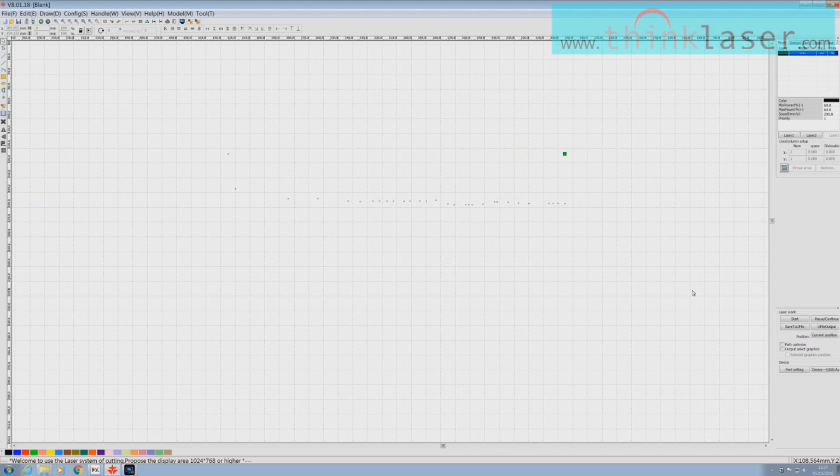with the keyboard. And then what I can do is box them all in like this. I can go up here to my commands, and first of all make sure they're all centered horizontally, and there we are, they're in a line. And then I can make sure that they're all spaced equally between the first and the last one, like that. So there are times when it could be useful using some of the tools that I've already demonstrated to you. There are other ways of producing this pattern of holes as well, which we'll get onto in the next session. So let's just ignore dots for the moment.